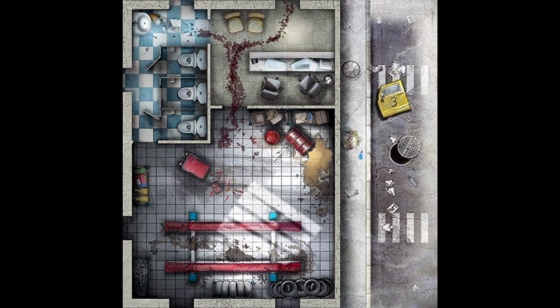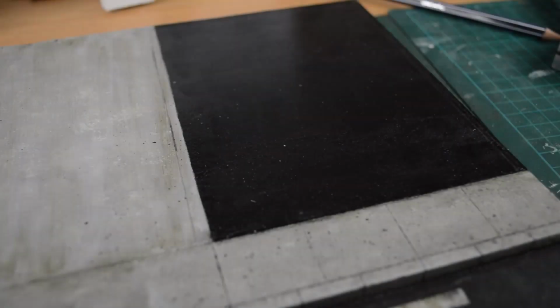Now for the floors. Based on the original tile, I decided that the office and bathroom sections should have tiled floors. I also decided that I would divide the office and bathroom from the garage section using a single straight wall, rather than the step section pictured here. Once I had decided on this, I measured out the floor space for each of the rooms, ensuring that I had left a 3mm margin at the sides and at the back of the tile for the external walls to sit.